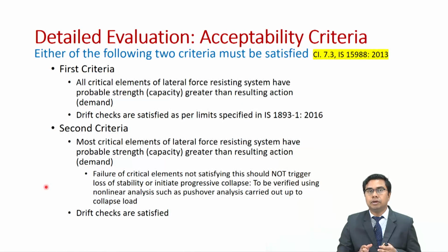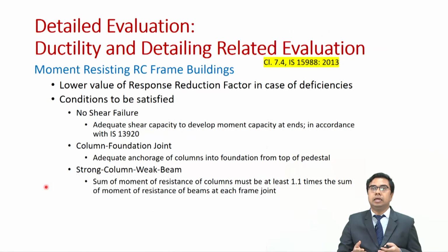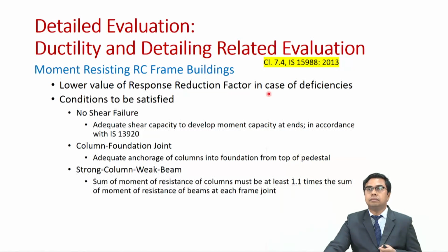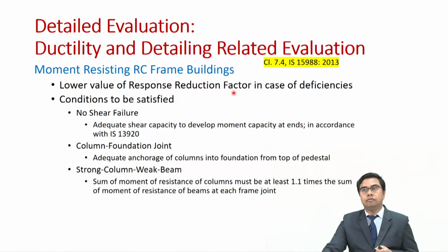Now, apart from the acceptability criteria, we will look into some more criteria which are related to ductility and detailing. So, in ductility and detailing related evaluation, let us look into the moment resisting RC frame building. In this evaluation, if you find some deficiency, then you shall be using the lower value of response reduction factor. The code does not give information about what the lower value shall be, but I hope for that you can refer to specialist literature.